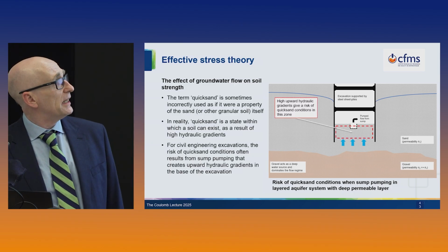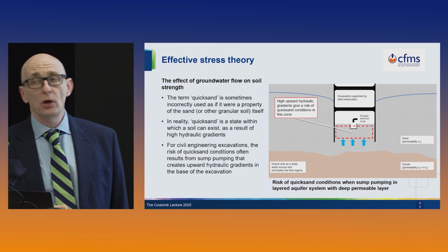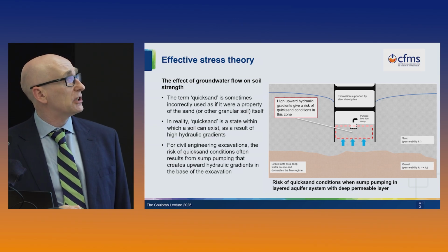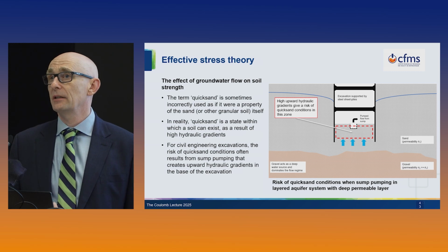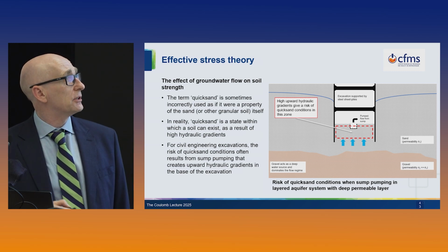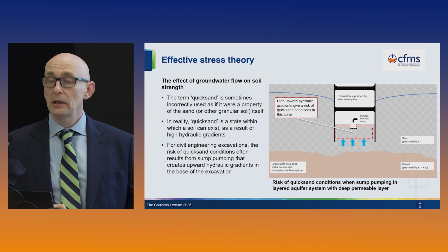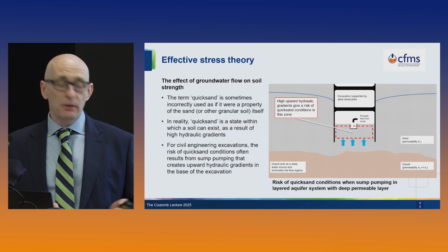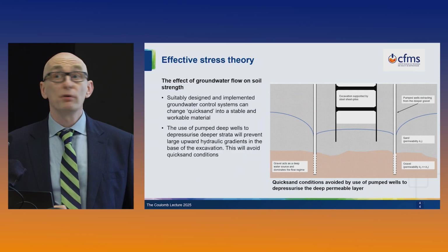And here there's a risk that in this zone you'll get a concentration of hydraulic gradients, and in that situation, because the total stress is low because you've unloaded the soil by excavating it, you can get low effective stresses and you can get quicksand conditions like the last picture in there. Of course, if we understand the ground conditions, we can prevent this.